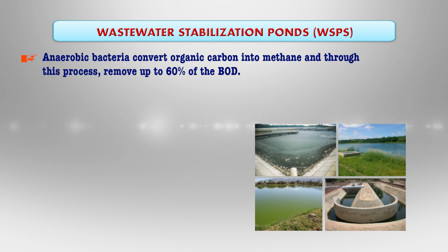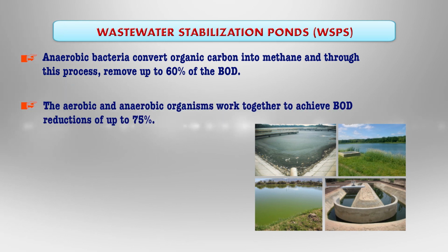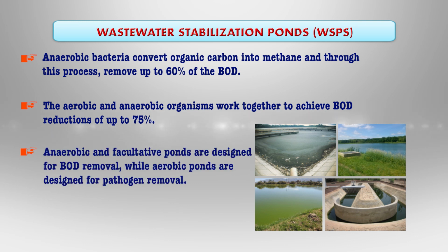The anaerobic bacteria convert organic carbon into methane, and through this process removal of up to 60% of the BOD can take place. The aerobic and anaerobic organisms work together to achieve BOD reduction of up to 75%. Anaerobic and facultative ponds are designed for BOD removal, while the aerobic ponds are designed for pathogen removal. That means there are specific ponds for specific purposes.